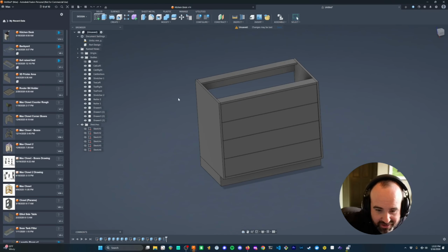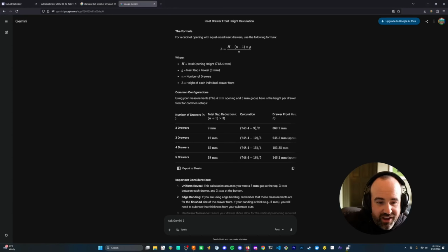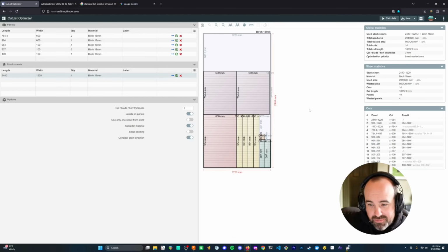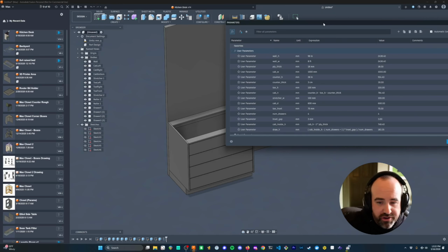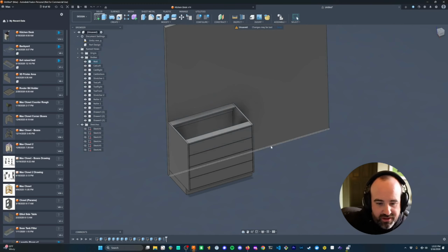So this is a basic cabinet design that I did in Fusion 360. I've got the cut list. I can print this out and then I can go and assemble it. And because I took appropriate measurements in the space, now I can say, okay, this should actually be correct based on the space that I have here. And I accounted for things like the countertop height. Remember, we did that in the beginning. We set the countertop height, 36-inch countertop height, 3cm counter thickness, and everything was kind of referenced off that to fit perfectly in the space.